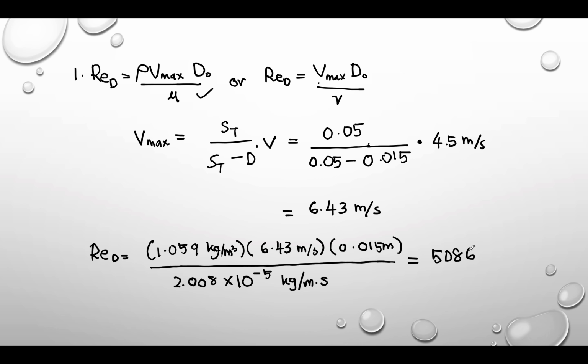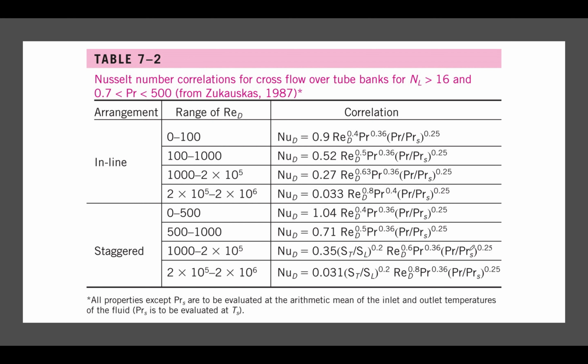Next, what you need to do is find which Nusselt number equation you need to select in order to determine the Nusselt number value. From table 7.2, we know that this question is for an inline arrangement.